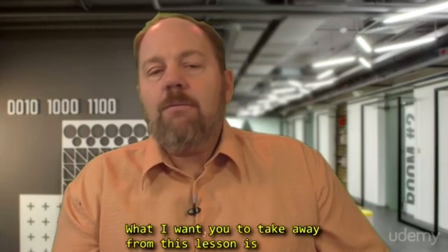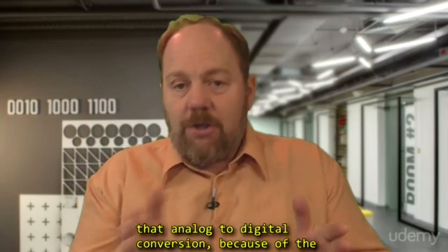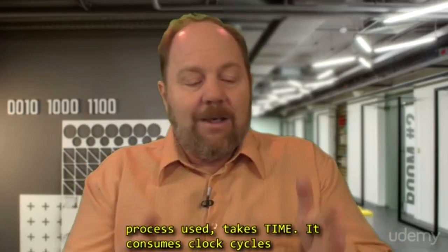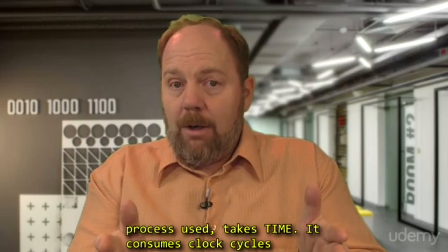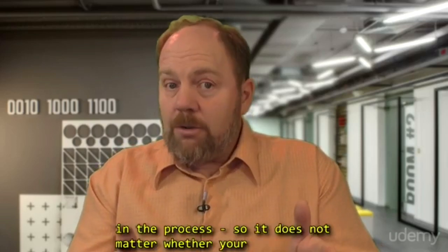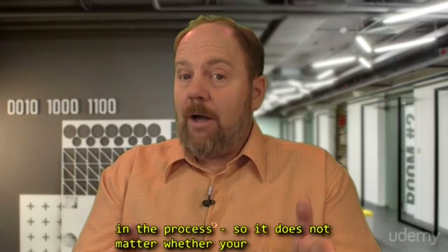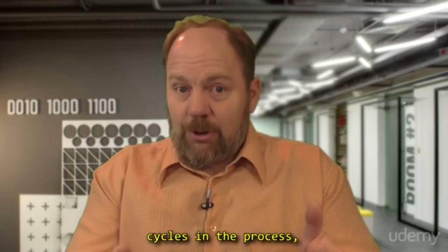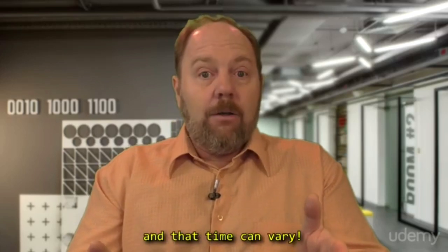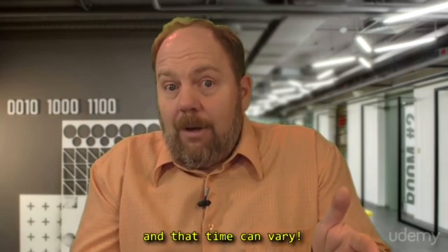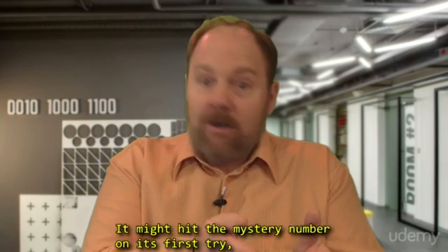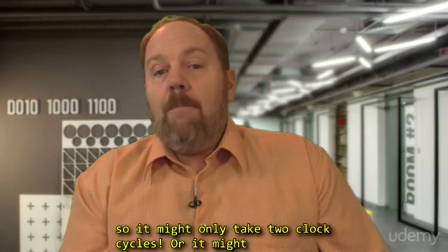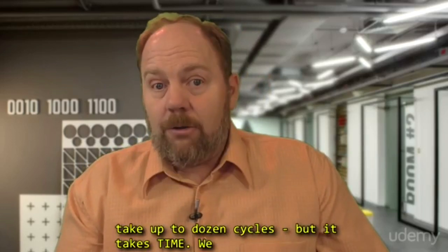Now, what I want you to take away from this lesson is that analog to digital conversion, because of the process used, takes time. It consumes clock cycles in the process. So it does not matter whether your clock is running fast or slow, it consumes clock cycles. And that time can vary. It might hit the mystery number right on its first try, so it might only take 2 clock cycles. Or it might take up to a dozen clock cycles.